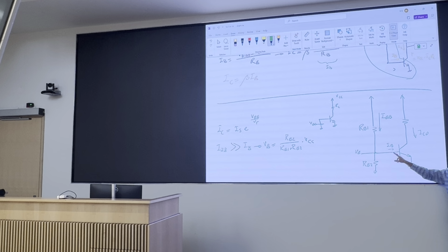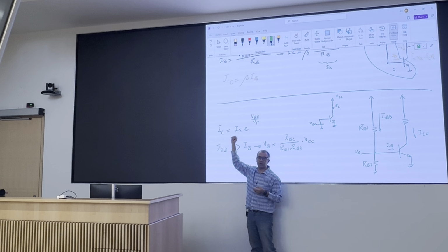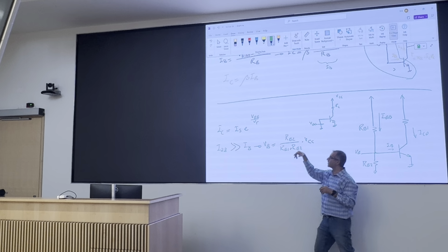What happens is that the current goes up, right? If you fix this voltage, this current has to go up with the larger IS because you're increasing IS, right? That's the temperature. So your current goes up. Your current goes up, what happens next? The transistor becomes hotter. Then what happens? The current goes up again. You have a positive feedback mechanism here. So this continues until your device is toast. Or your power supply doesn't have enough current to do it, but usually your device gets that. So it's delicate.